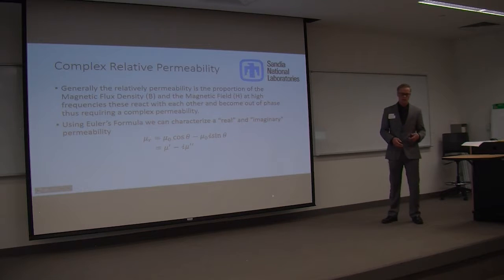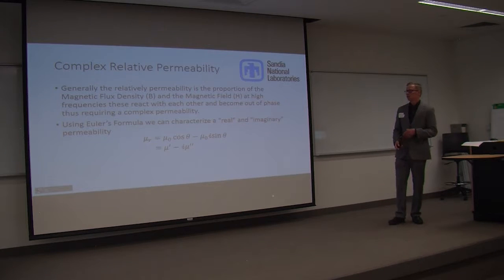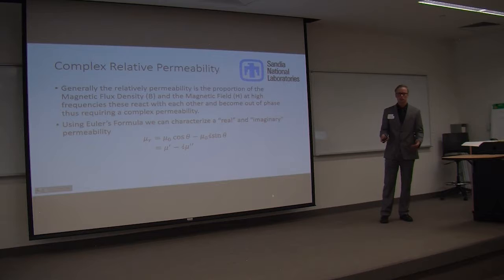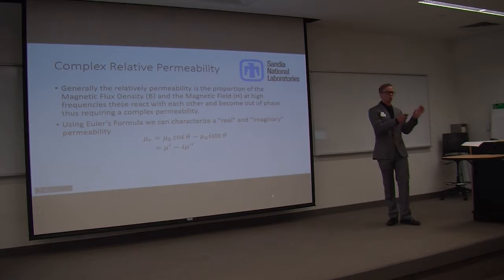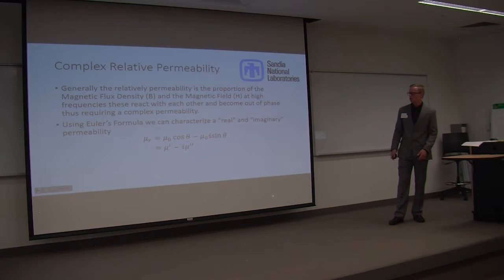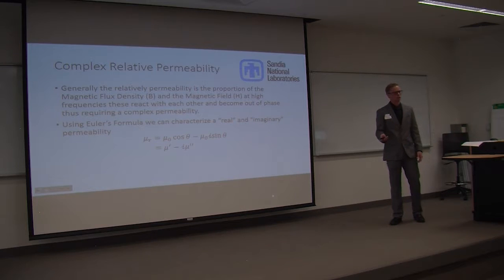And the next part is the complex permeability. We can input a relative permeability that we're given with the material itself when we buy it from the producers, and that's just 2,500. But because we're running it at such high frequencies, we get a real and an imaginary permeability. You might think, how can you use an imaginary permeability in your model?